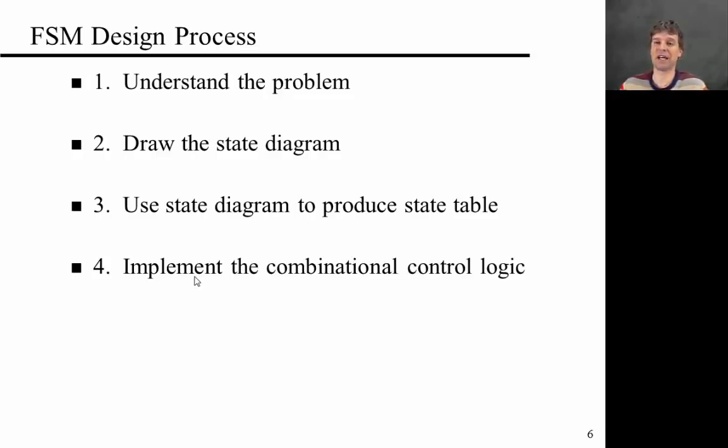Like from the state diagram you can derive a state table. It's completely automated. You just read off states and the values you've written on the arrows. From the state table you can use everything you know about Boolean minimization to derive a minimal combinational logic circuit, and then you can just actually build the sequential logic device.